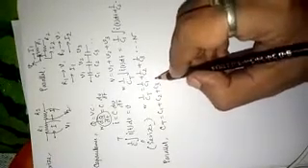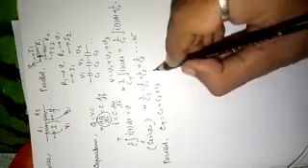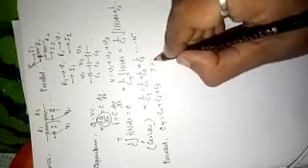Now if you are taking a parallel combination, obviously the reverse case will come. So Ct equals to C1 plus C2 plus C3. Now you can ask me why. Because in the parallel case the voltage is the same, so this V is the same, but what is different is I. So in the parallel circuit you know that I equals to I1 plus I2 plus I3.